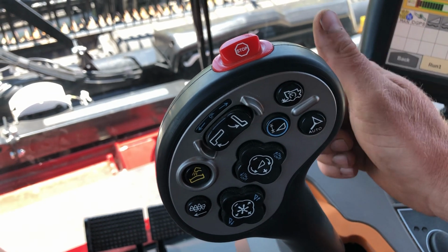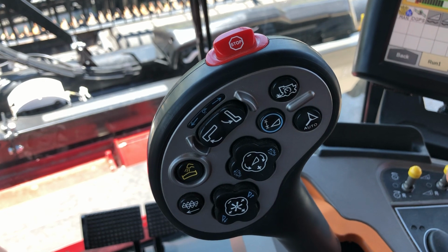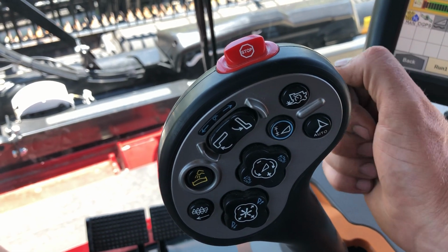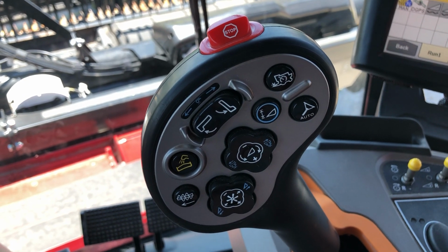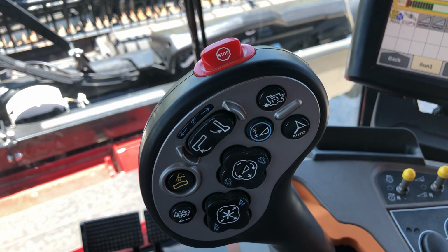Versus if I go up to that 5 miles per hour or close to it, click my button, and then I'm harvesting at 5.5 miles an hour and I wiggle my hydro handle a little bit, I'm only decelerating 0.5 mile per hour as I disengage from feed rate.